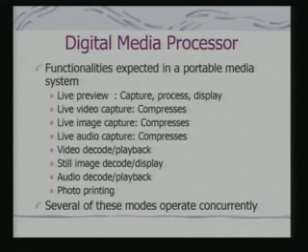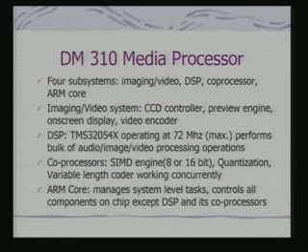And in fact, this kind of commercial interest actually drives these manufacturers to visualize and design this kind of multiprocessor application platforms. They have provided the platform, and others would be building systems around it. So, here is an example of what I have stated: the functionalities required, and several modes would operate concurrently. And taking this into account, there is the DM310 media processor, which is again an SoC, a multiprocessor SoC, and it has got 4 subsystems: imaging and video, DSP, a set of coprocessors as well as ARM core. And you will find that ARM core is being used in a very extensive fashion.